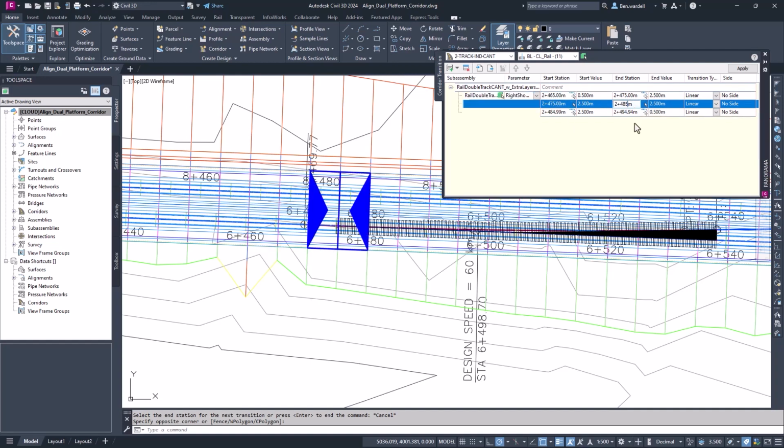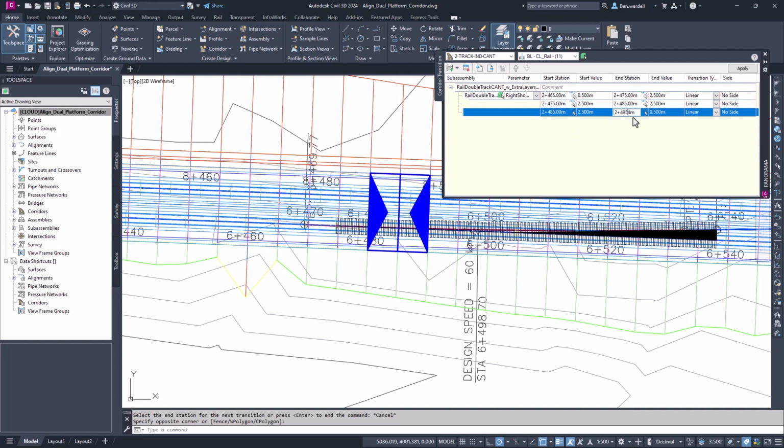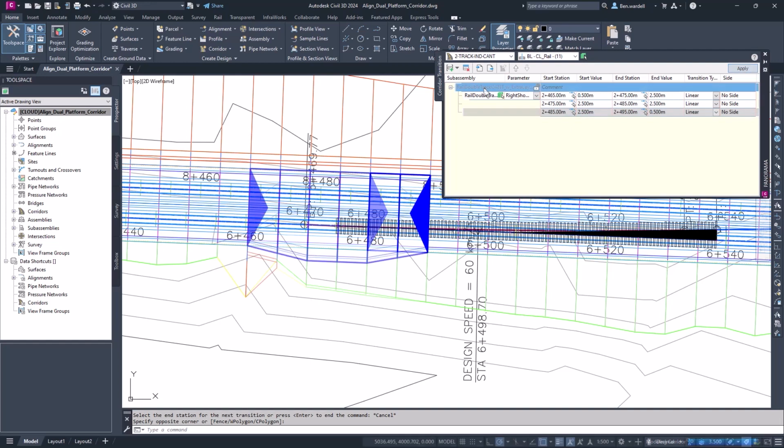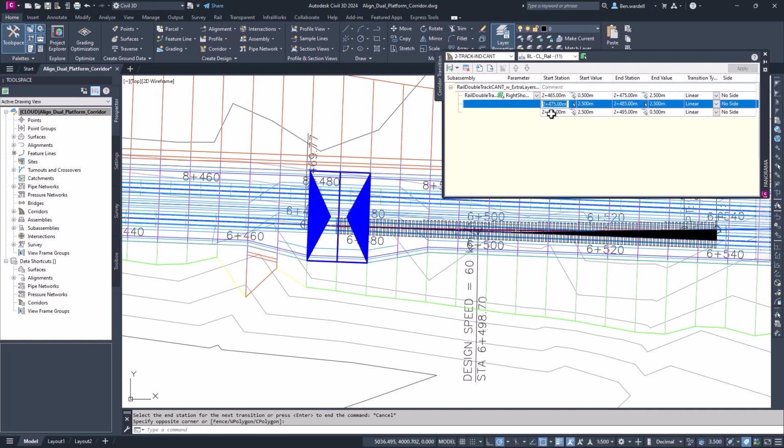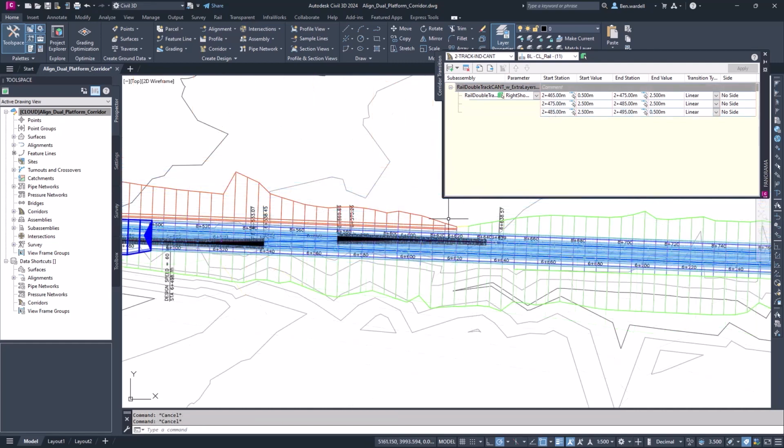And we'll make these numbers easy, and we'll round up to the nearest 10. Then we'll choose Apply. Once we do that, we can see each section in our plan view, or we can view the entire set. So now let's copy this for the other area. We'll give that a name first, and we'll lock it so that those transition spacings will stay the same.